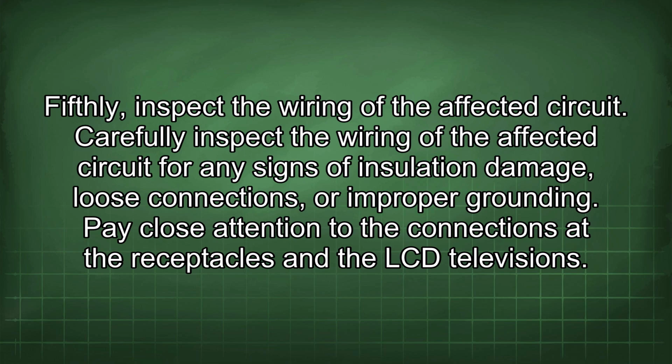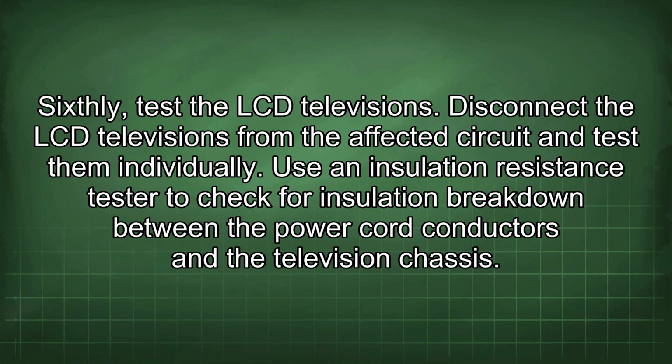Fifthly, inspect the wiring of the affected circuit. Carefully inspect the wiring of the affected circuit for any signs of insulation damage, loose connections, or improper grounding. Pay close attention to the connections at the receptacles and the LCD televisions. Sixthly, test the LCD televisions.